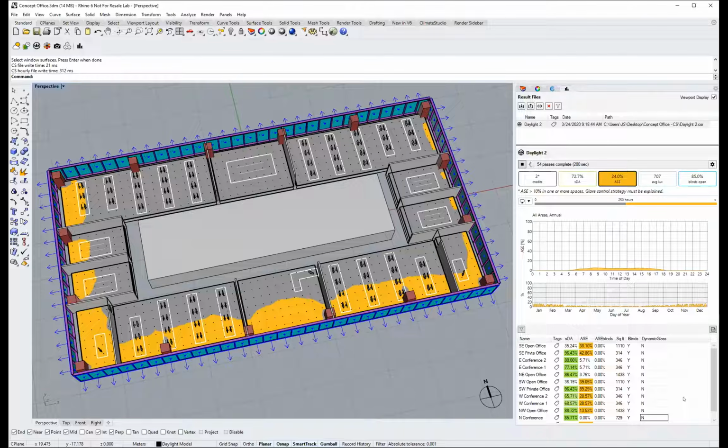So one is if we are relying entirely on a specification of automated shades to get our LEED points, we're putting in the hands of an item that can easily be value engineered at the end of the project, all our hopes and dreams. So this maybe isn't the best and most integrated design strategy. It's also, frankly, just bad daylight design.